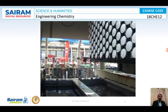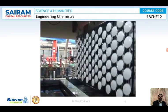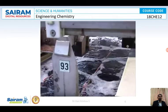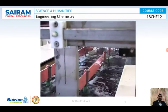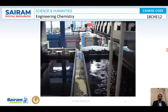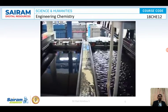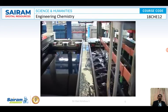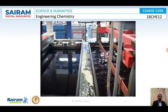Catalyzing the plastic with the controlled adsorption of palladium and tin colloidal particles in the micropores is critical for making the surface conductive. The next process is referred to as accelerating the surface, where a chemical reaction takes place to oxidize tin plus 2 ions to tin plus 4, and palladium ions are deposited on the surface as metallic palladium.